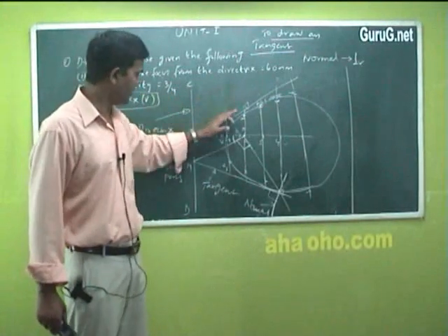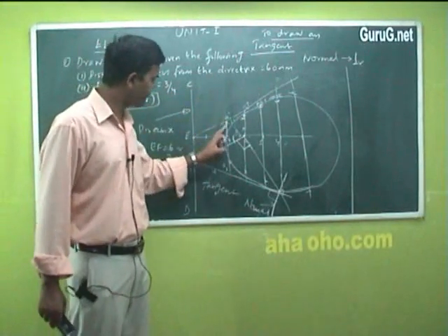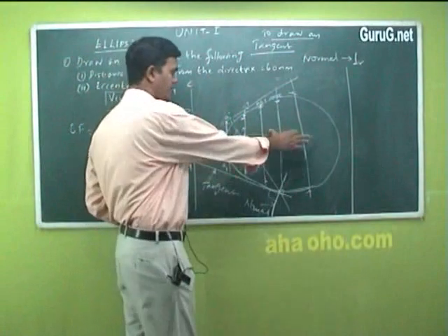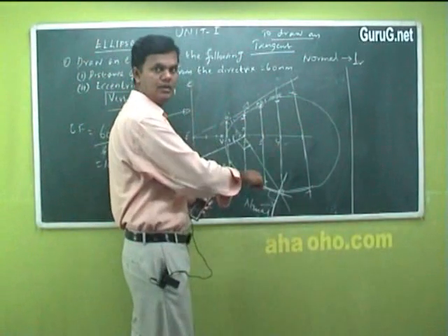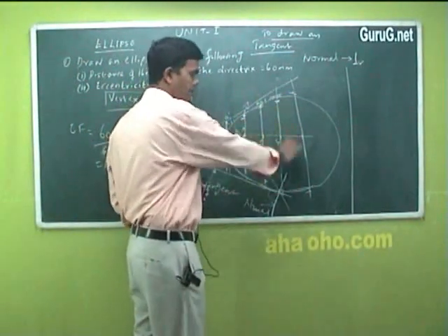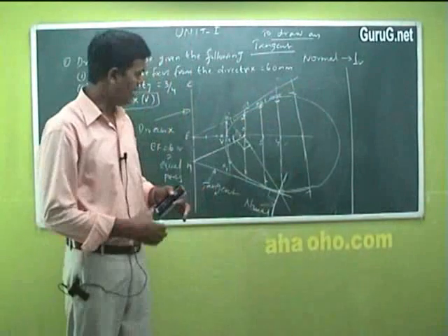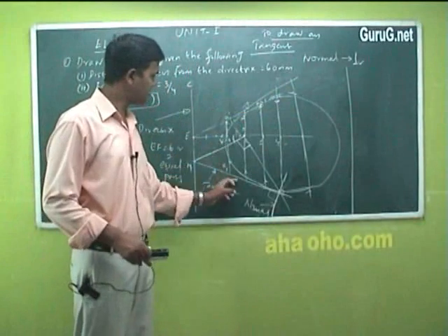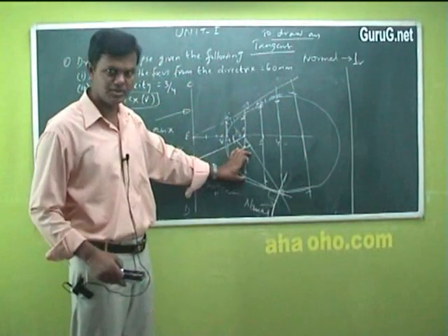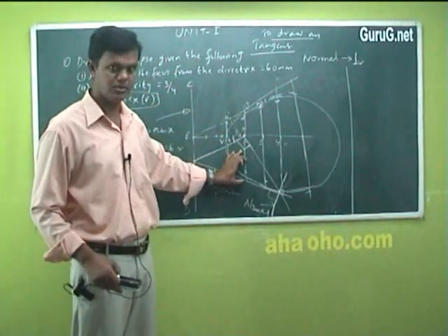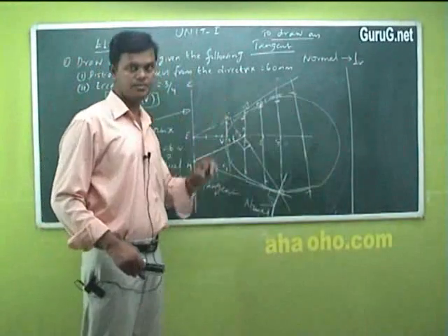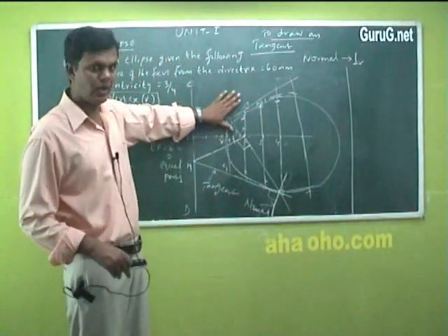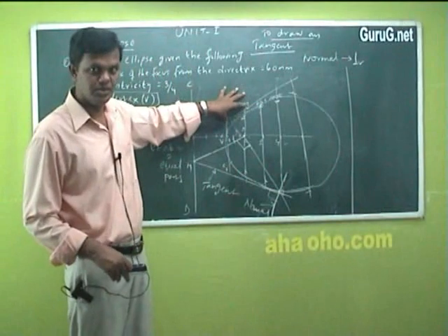After that you divide the remaining line into a number of equal parts, draw perpendicular straight lines at those parts, measure these values and keep on cutting at this point. The opposite side will be the same: if this is 1 centimeter, this is also 1 centimeter. You make a curve. If you try it on a drawing sheet, you will usually get a perfect sketch.